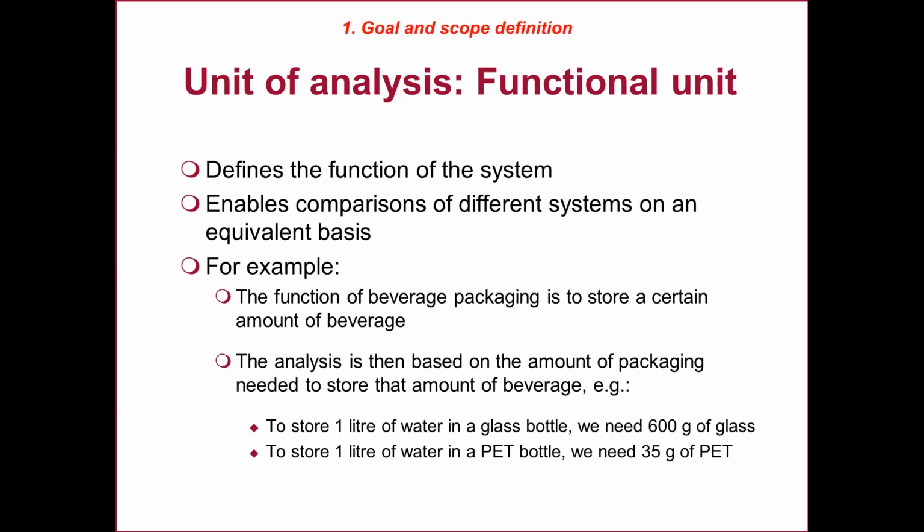High quality paint may give us a higher surface area, and it could last longer before we need a recoating compared to the average quality. In that sense, we would have to take into account, maybe we want the functional unit in terms of surface area over the lifetime. We say, okay, we want 10 square meters of a wall over 10 years of time, then we calculate the amount of paint required and assess each of them and compare them.